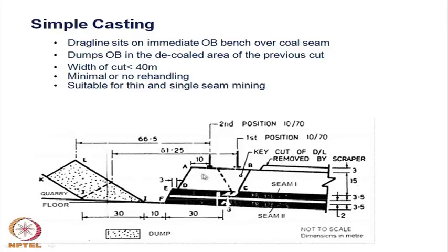Now when the next block is cut, another spoil dump will come over here. Then you use a dozer, and that upper triangle part can be made a fill over here, and then we can level this spoil dump. That is a different issue. We will be discussing how we manage spoil dumps later on.